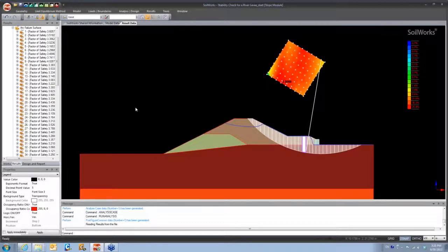And then what the program actually does is it takes the deformations, the shear strains, etc., for each of those stages, so you can see how your construction site changes with time. And also if you have temporary support structures, for example a retaining wall that's supporting an excavation, or maybe tiebacks, you can model those temporary support structures through various stages as well.